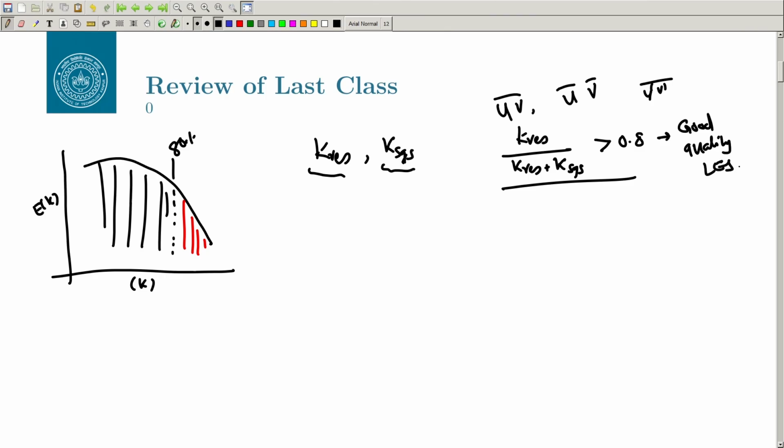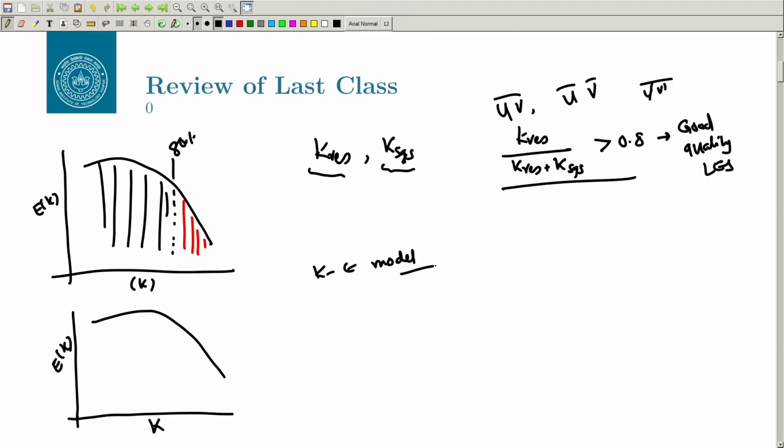So, this you can check once you have already performed the LES. The other thing we discussed regarding LES is how you decide the grid size before starting LES. Typically, you perform a RANS simulation, and from the RANS simulation, depending on what model you are using, let us say the k-epsilon model, you can calculate the length scale.